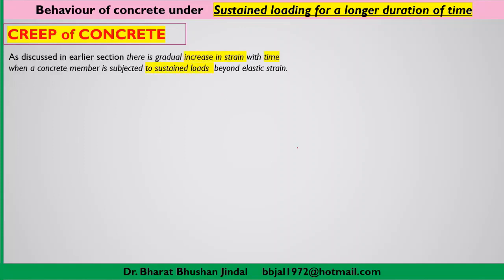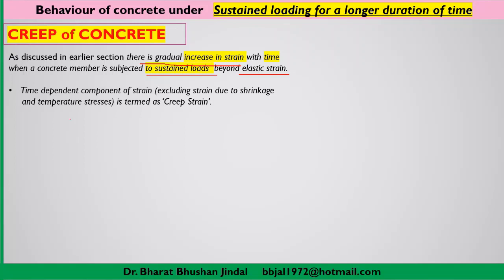Now, as we have discussed in the previous lectures 1 and 2, there is a gradual increase in strain with time, which you can review from the stress strain graph. So when a concrete member is subjected to sustained loads beyond elastic strain, what will happen? Then we can understand that another important aspect is creep strain. That means it is a time dependent component of strain.